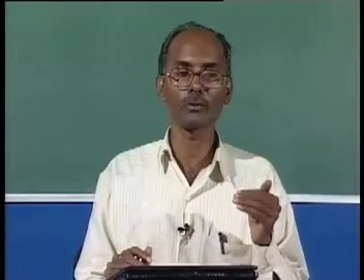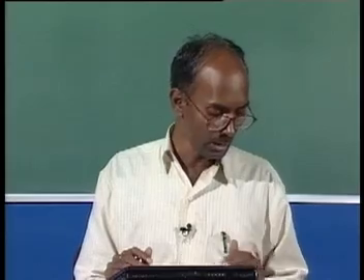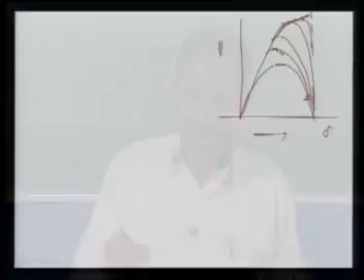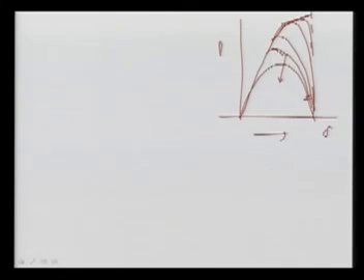Now if the limiting value is hit, meaning if the value for the SVC is hitting its limit, then what will happen? This is your pi by 2. As I said, here it will be like this. The characteristic will finally be here. So where it hits depends on the VC max, this is nothing but your VC max, the total VC max you are achieving, and then you get this characteristic. However, in this STATCOM, what we are going to get, again I will compare this.